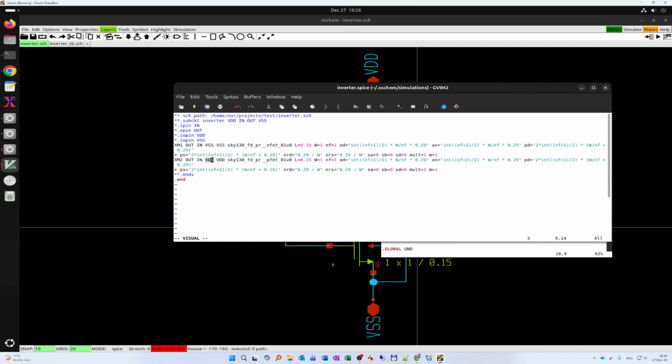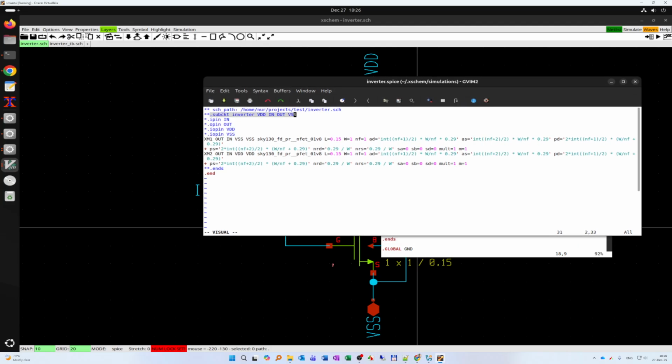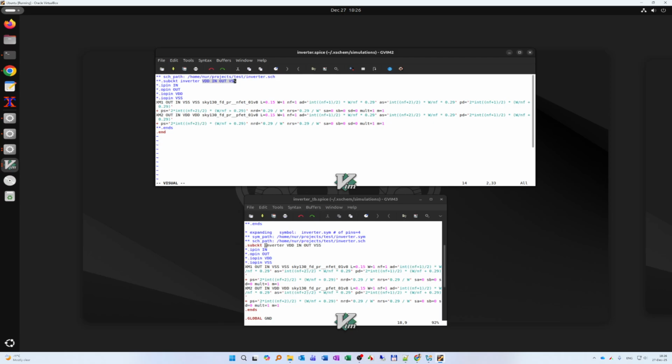For the layout, I'm going to follow this subcircuit because when we do the post layout, we should follow this one. Anyway, when we extract the post layout netlist, we can still edit the text file if there's some mismatch.